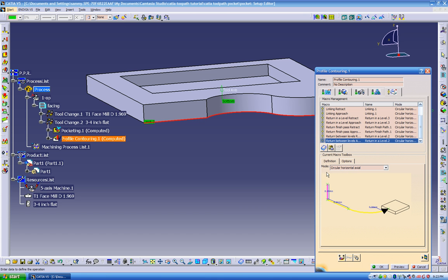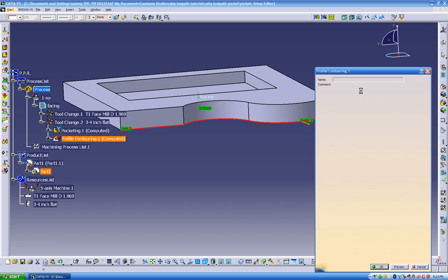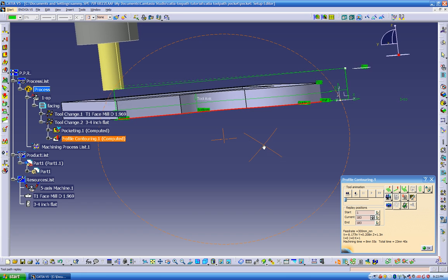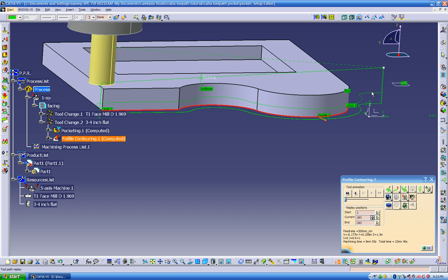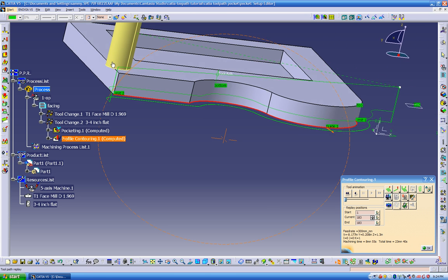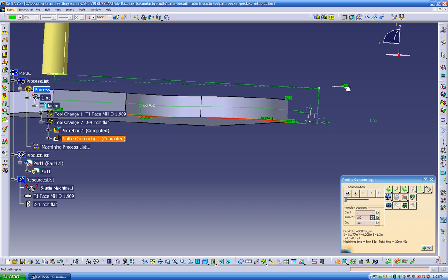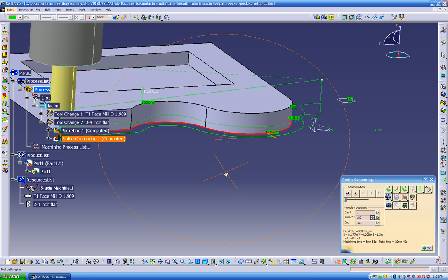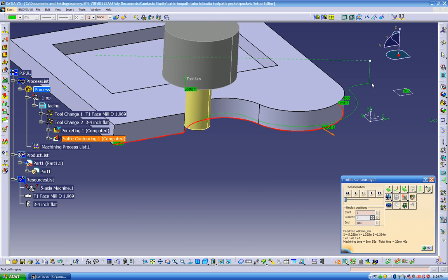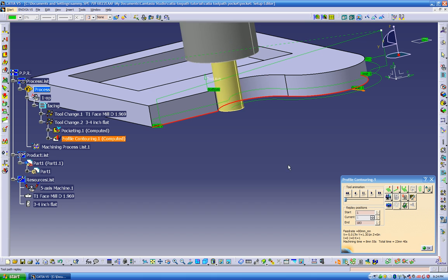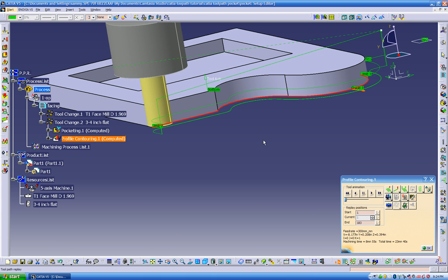And also we can add planes to these guys. You can go back, build by user, click on the plane, select your plane, and also you can do this. So we can bring your tool all the way to the top. So see right now how nice it looks. Every little pass leads outside, come back in, it goes all the way to the top, which is this plane that we selected. And this is beautiful. So let's watch it. See, plunges outside. We got 2 roughs, and this is 1 finish.